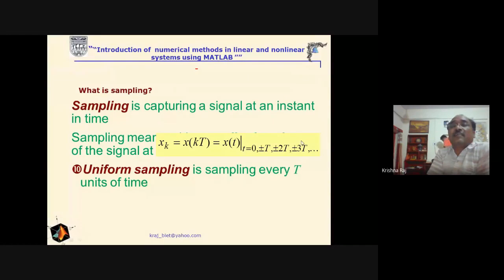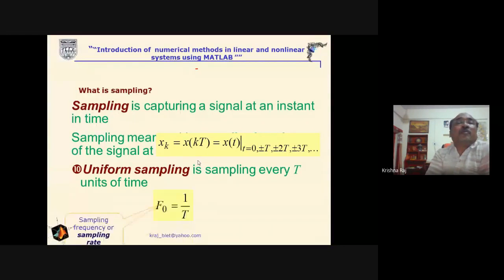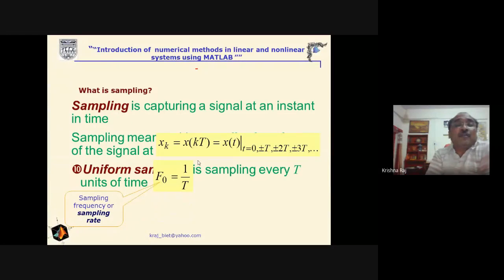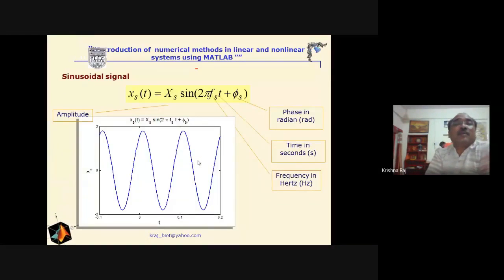This discretization is done with the help of sampling, which is covered in the electronics field. The advantage is that the processor or system will not work for every instant, so multiplexing can take place. At the same time, different happenings or different signals may be processed by the processor. And the sampling frequency is just the inverse of the sampling interval.